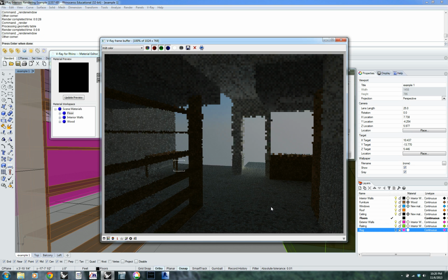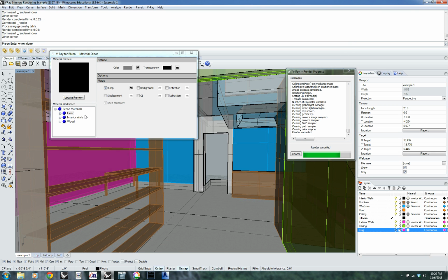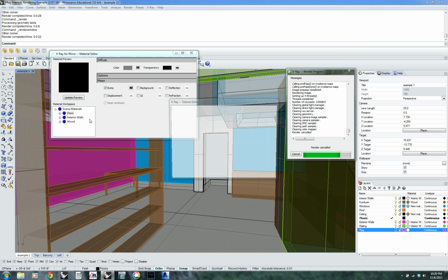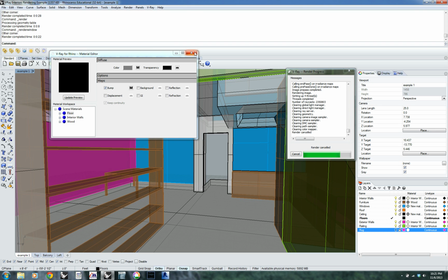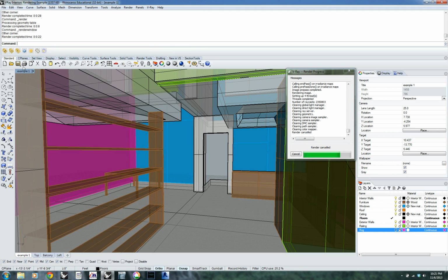Let's see what the scale is. So that's looking pretty good. It's looking like kind of a smaller textured tile. And that looks pretty good. I think I'll accept that, and you can see with the bump it gives it a nice texture. That's looking a little strong right now, so maybe I'll come in here to adjust that bump. You're going to adjust the multiplier, and so maybe I'll make it 0.5. That'll really tone that down a lot. Okay, so that's looking pretty good.